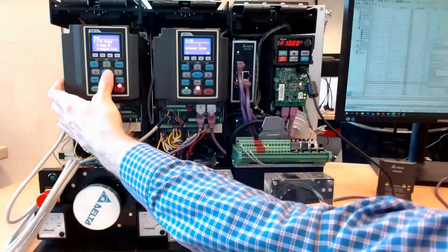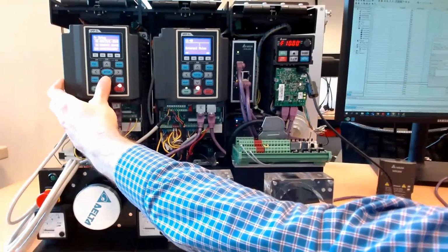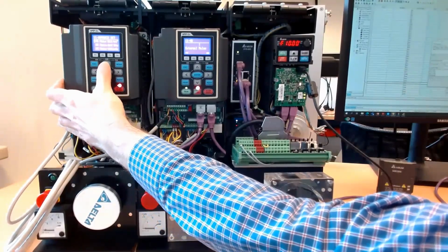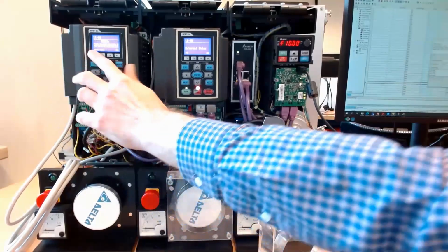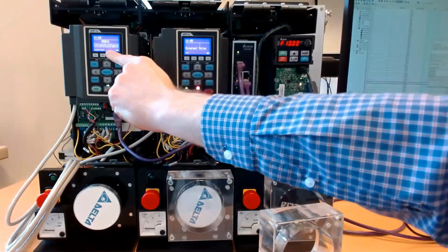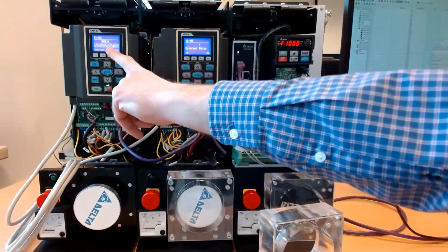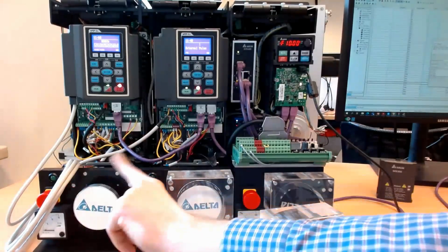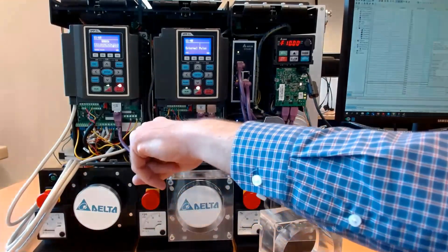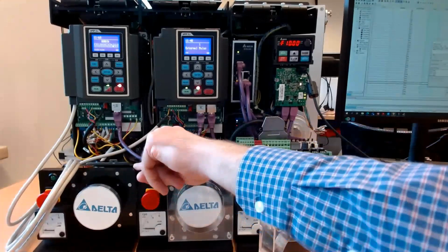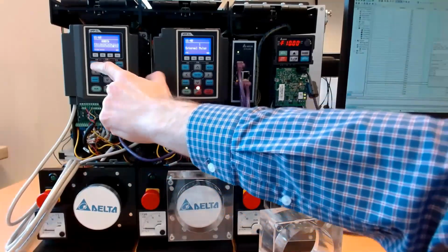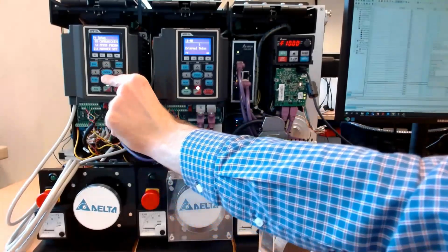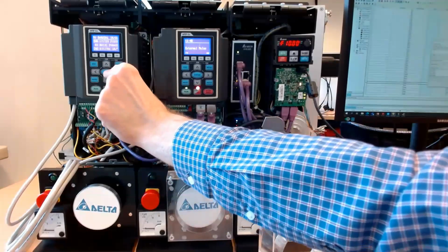In order to do the homing, firstly, you need to check which homing method you want to use. You can do that in parameter 1168. Currently, this follows the DS402 standard. So homing number 8 means that the drive will just set the current position as the home position. But you can also do the homing based on negative limit, positive limit, or origin. I will just leave this at its current value at the moment.